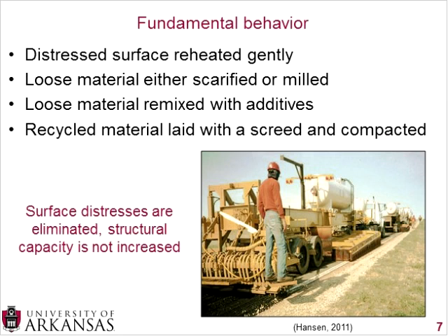So the fundamental behavior behind these processes is you want to make sure you reheat the material gently. If you Google HIR and look at images, you'll see some with flames literally coming out from underneath the heaters. If you have an unqualified crew or inappropriate equipment, that is a possibility, but you don't want to go there because then you just end up burning your asphalt, which degrades it even further. So you want to gently reheat it in order to rejuvenate that asphalt binder in the upper layers.